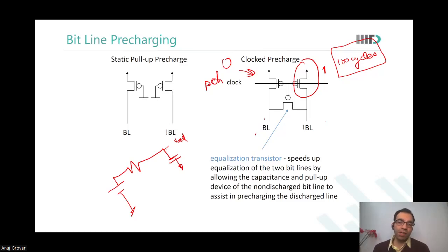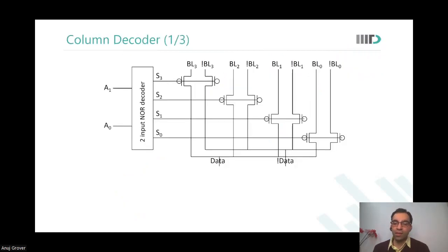Yes, the write driver will turn on after the precharge goes off, before the word line comes on. Only after the bit line has discharged will the word line start to rise. Okay, sir.